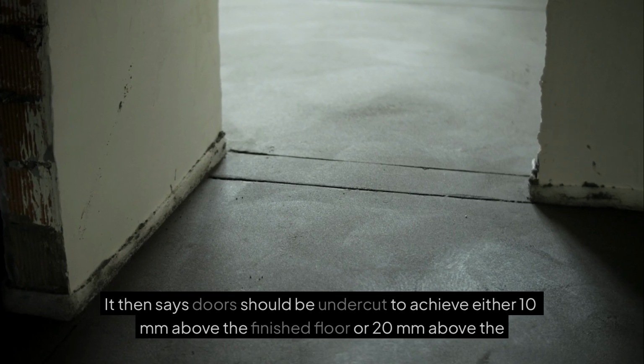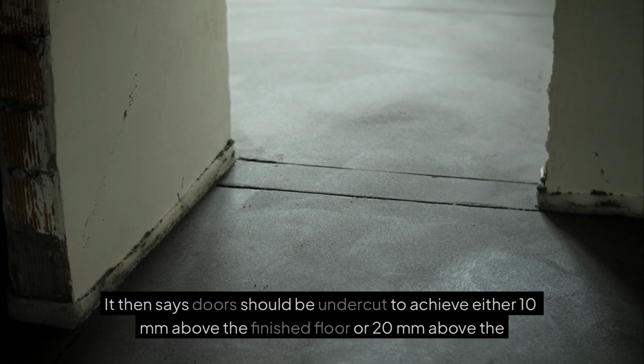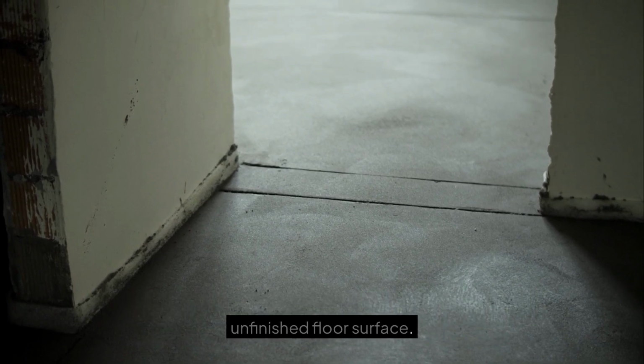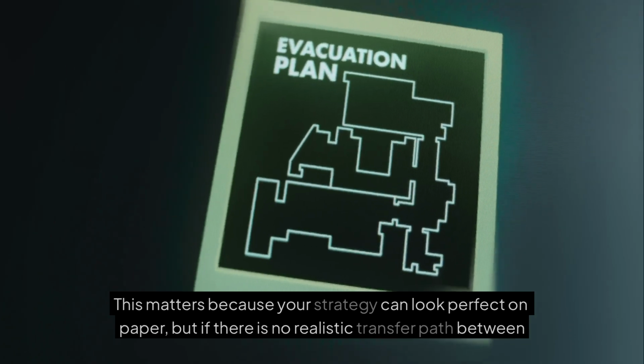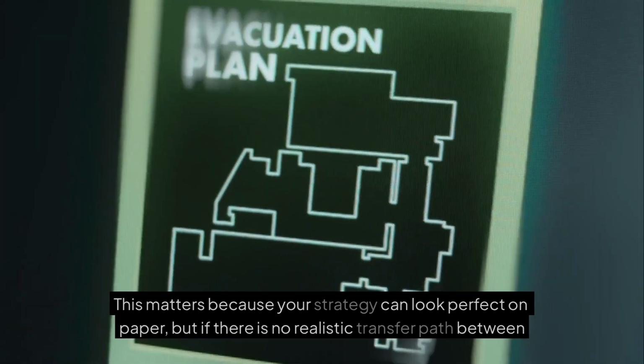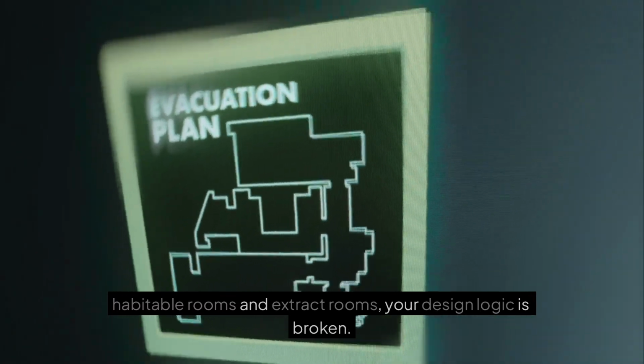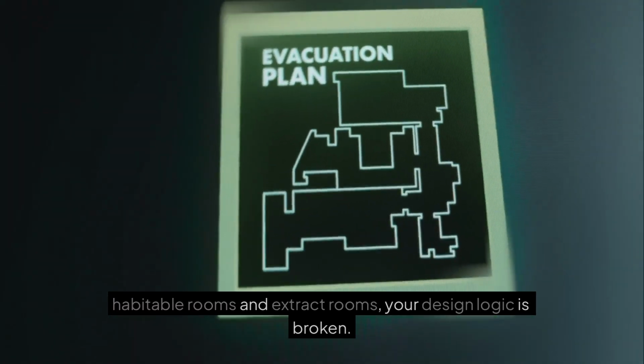It then says doors should be undercut to achieve either 10 mm above the finished floor or 20 mm above the unfinished floor surface. This matters because your strategy can look perfect on paper, but if there is no realistic transfer path between habitable rooms and extract rooms, your design logic is broken.